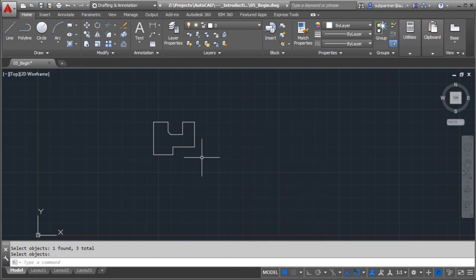So there's a look at how we can basically get started drawing lines. We know how to draw them kind of organically by clicking a start point and an end point. We know how to draw them by specifying a distance. If I want to start at one point and I want to go out 18 feet in that direction, we know how to do that.